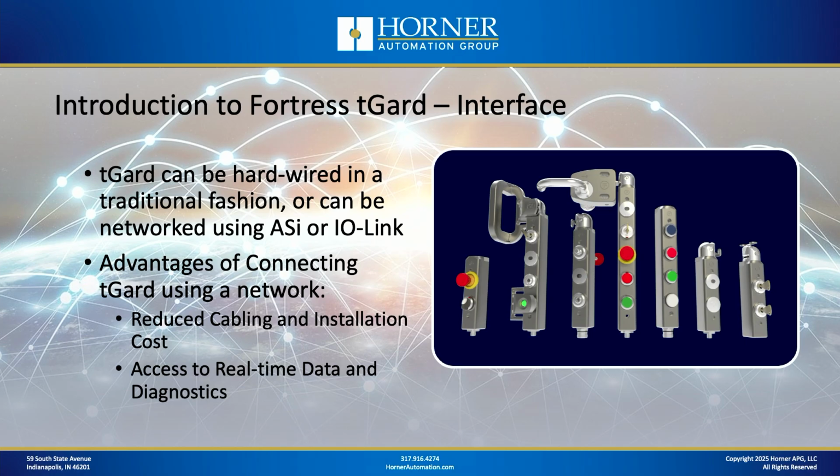Now, the advantages of connecting tGard using a network like ASi or IO-Link are several, but here's a couple of them. It reduces your cabling and installation cost, and it gives you access to a lot more data and certainly a lot more diagnostic data than you would get through hard wiring.